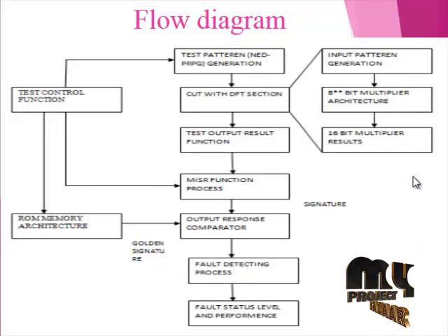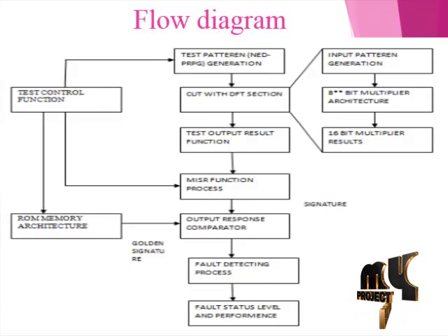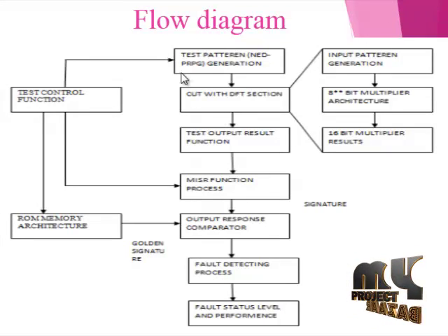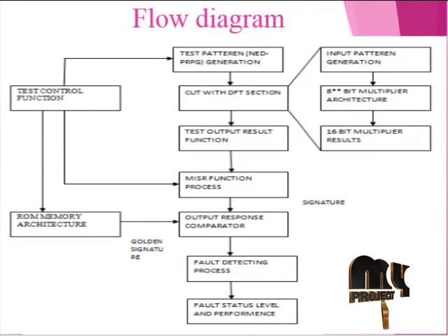Test pattern generator generates the test patterns for the CUT. It is a dedicated circuit or a microprocessor. The patterns may be generated pseudo-randomly or deterministically. Multiple input signature register is designed for signature analysis, which is a technique for data compression. MISR efficiently maps different input streams to different signatures with very small probability of aliasing. MISRs are frequently implemented in built-in self-test designs in which output responses are compressed by a MISR.